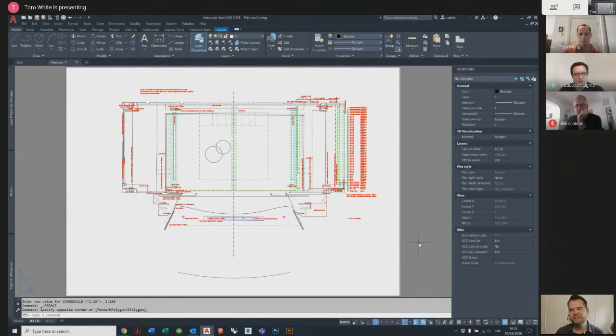One thing I would say to people who are making scales up: make sure the scale you put in your viewport is the scale whoever's on the end of the line has on their scale ruler. Don't invent some funky scale. That's exactly what I do. So I always stick to the scales that are on my old school triangular scale rule. You can have 1 to 25, 1 to 30, but also equally 1 to 25 multiplied by 10 can be 1 to 250, 1 to 30 can be 1 to 300. But don't go back with 1 to 28. You will not be thanked.